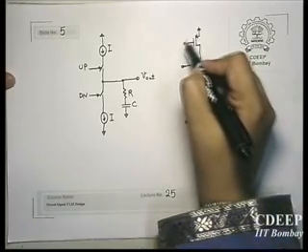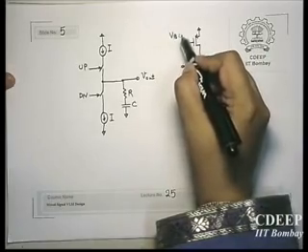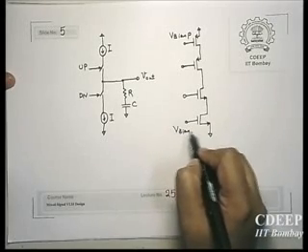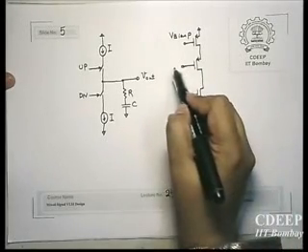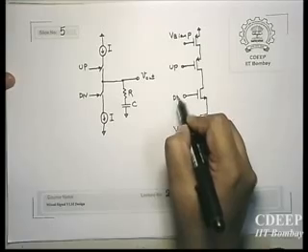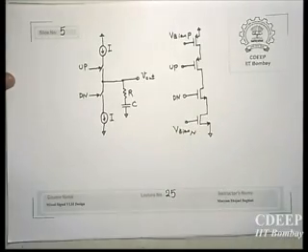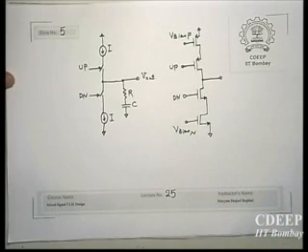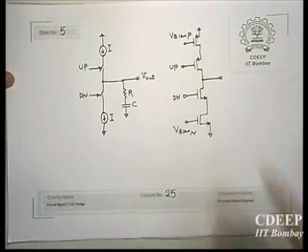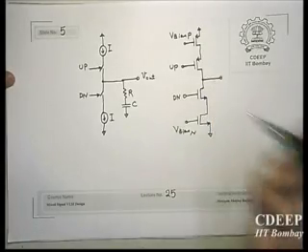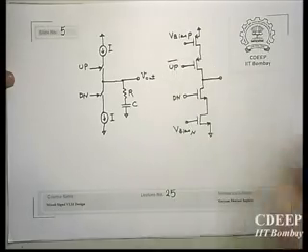So for example, you have V bias P, V bias N, and then you have up, you have down. But of course, if it is like that, this up and down won't work, because what you want is that when up is 1, you want this to source the current. Therefore, you need to make this up bar to operate.